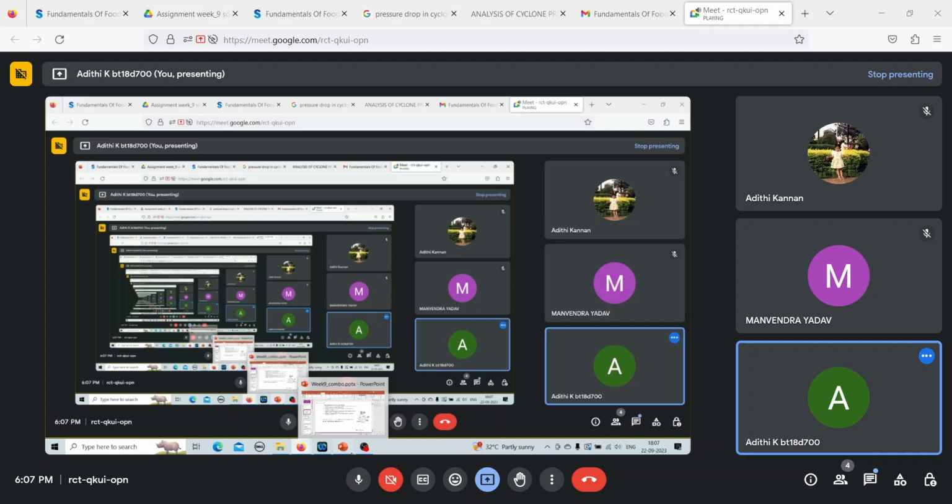And then the driving force for cake filters is a pressure difference across the filter medium and the cake deposited on the filter medium. So it's basically like filtering out tea or anything, the basic examples that we see here. So the driving force is the pressure between the outside of the filter and the pressure that you're giving on the filter. So that pressure will be the pressure difference across the cake that is being deposited as you keep filtering your slurry, and across the filter medium that has your membrane or any other material that is used for separating your materials. So the answer here is option B.